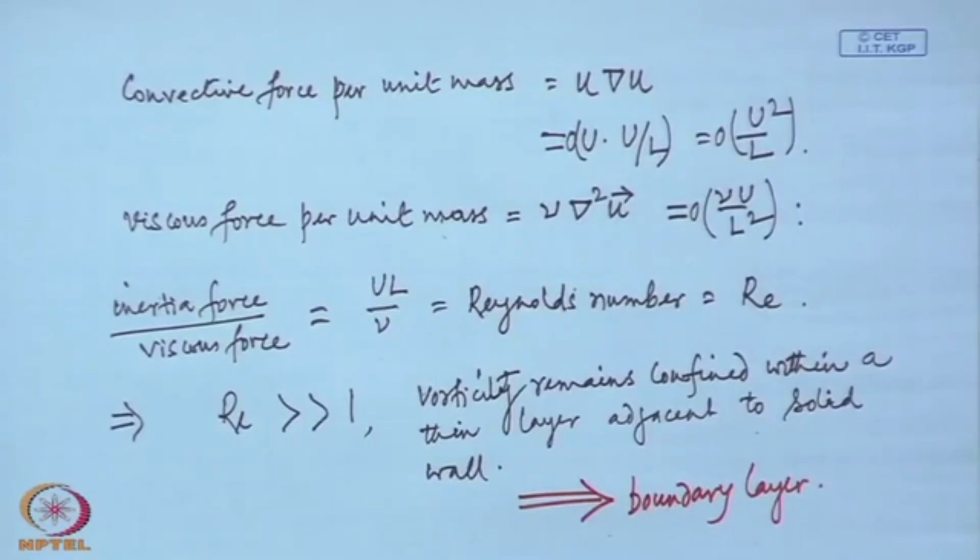So, for a high Reynolds number flow, a boundary layer develops over certain geometries, and within this boundary layer the velocity changes smoothly from 0 on the surface to the inviscid flow velocity at the edge of the boundary layer, and within this layer the vorticity is non-zero, the flow is rotational. And so, think that when the Reynolds number is really large, considering practical aerodynamics where Reynolds number is of the order of 10 to the power 7, 10 to the power 8, then the inverse square root of that is practically very small.